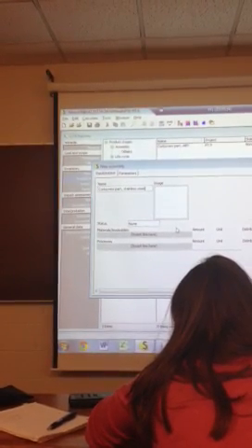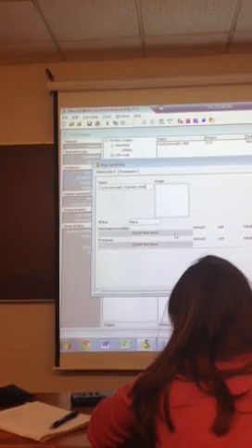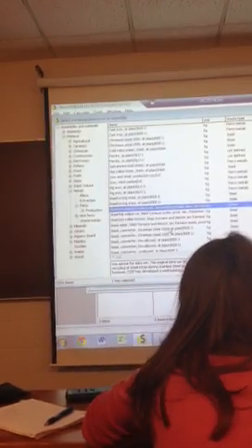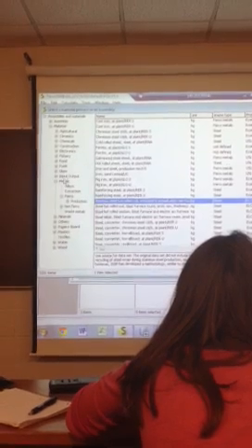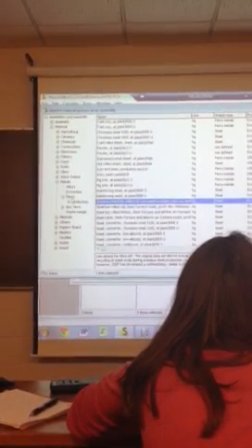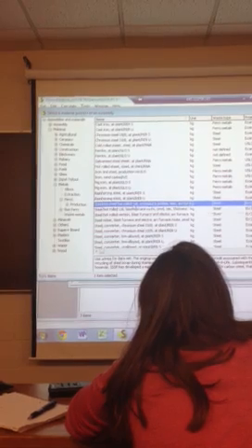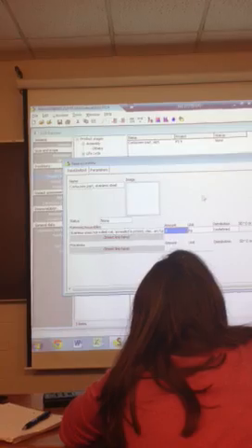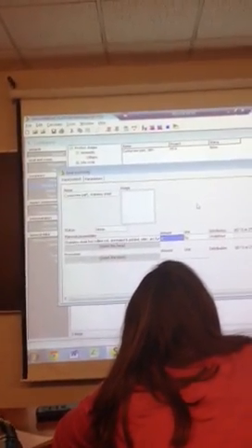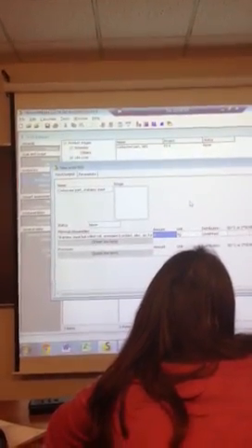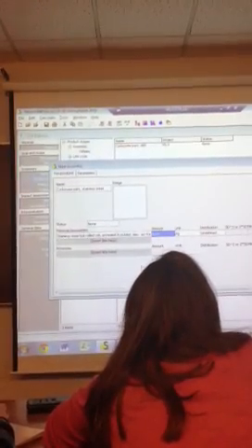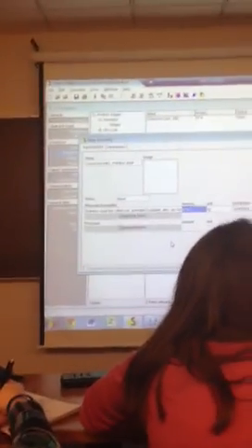So basically whenever you want to add on something, you'll double click where it says insert line here and just find where it is in the thing that opens. So here you want stainless steel, you go under materials, metals, ferrous metals because it's an iron, and there's basically only one thing for stainless steel. So we'll select that, and then we'll input the mass that we got from our Excel solver. So when I did that, I got 0.23 kilograms, so I'll put in 0.23 kilograms. Done. And then we'll add in those three processes.